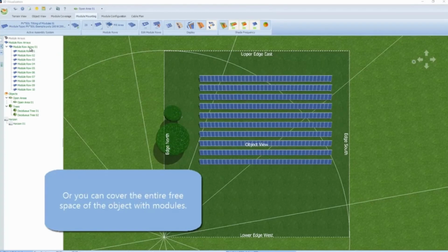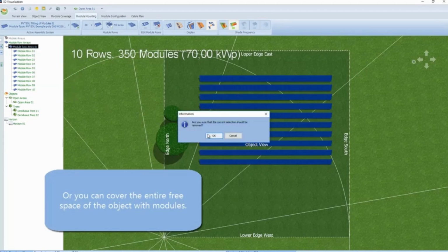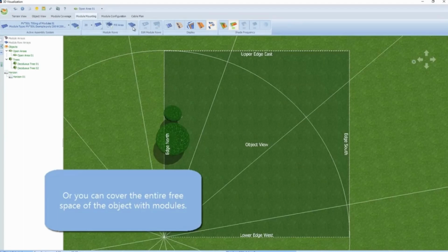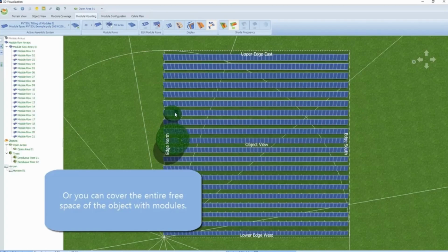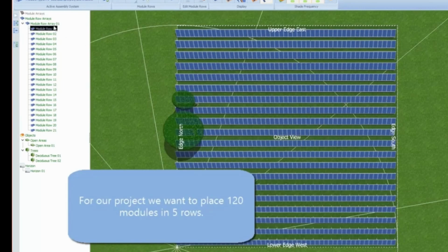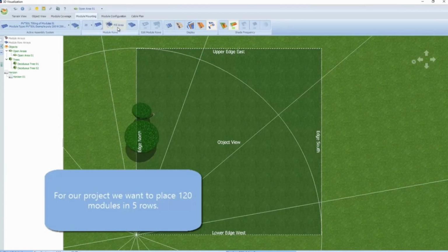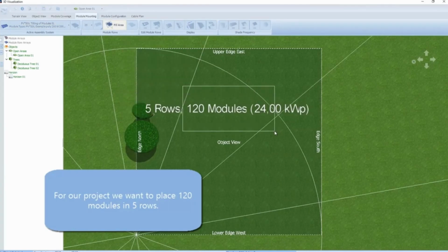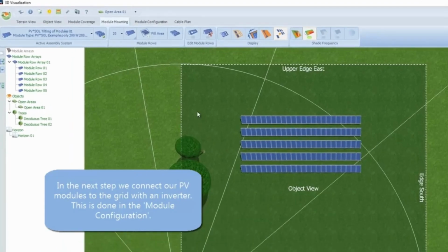It also does a calculation of the shadows, and the losses per year are usually indicated by color. So red color means severe shadowing, severe losses, and green is no shadowing and so on. We see it later. So we see here some modules are subject to shadow now. Now we can do a calculation during a whole year and see the different losses. I know it's not done here. You see the different configurations first here. Different distances between the rows.